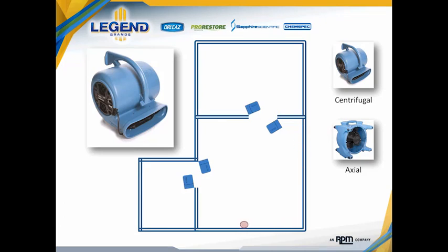What we use to deliver the heating or cooling throughout the entire building is ducting, what we call supplies and returns. The ducting pulls air out of rooms, brings it to the heating system, and then brings the heated or cooled air back to those same rooms. And that's essentially what these air movers are doing for us. They're using the wall assembly, the footprint or the layout of the rooms, as a ducting system to evenly distribute air throughout the space or throughout the property.